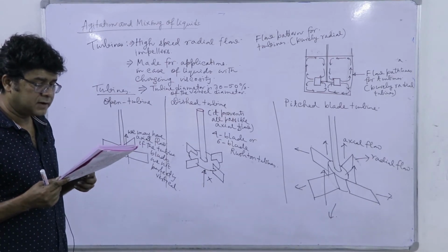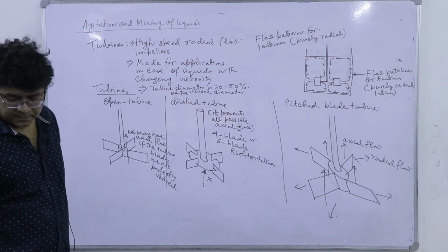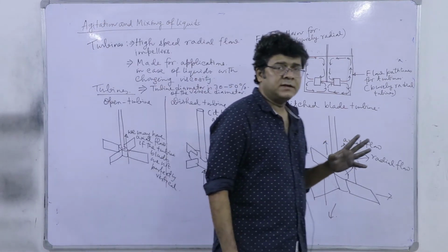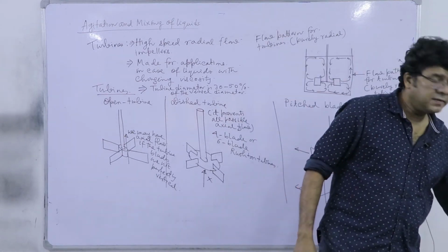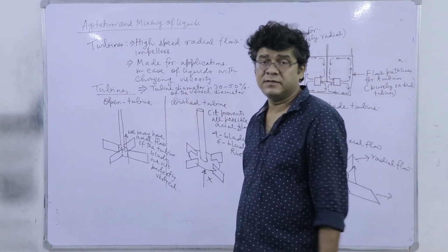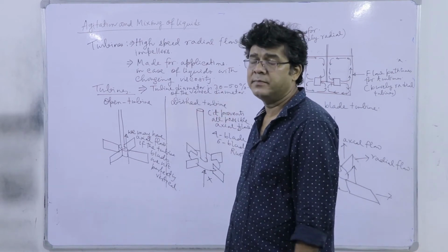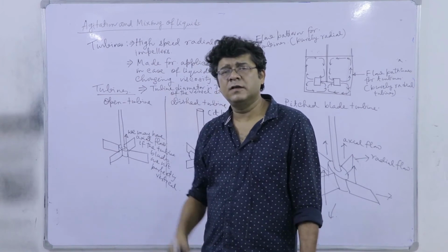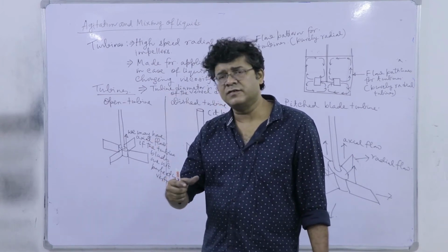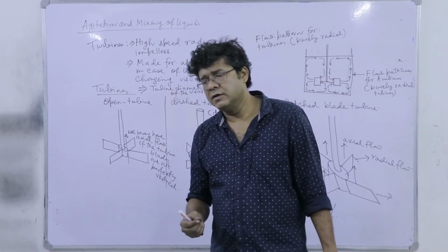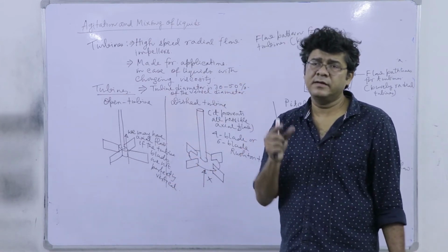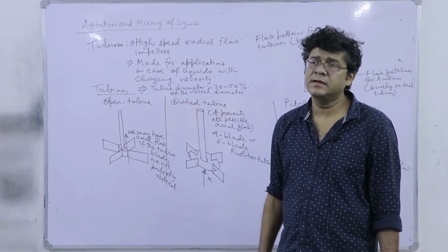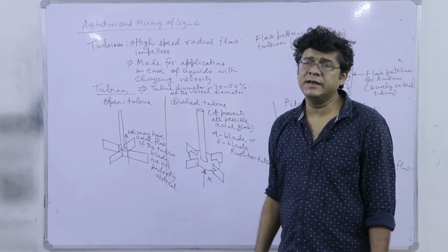The basic flow pattern of the liquid in a standard turbine is shown. Now, we have to justify why we use these baffles. In the diagram of these agitators, I have shown that we are using some rectangular shaped strips, which have very small thickness and whose height is nearly equal to the height of the liquid pool in the tank, that we simply weld on the inner surface of the tank.